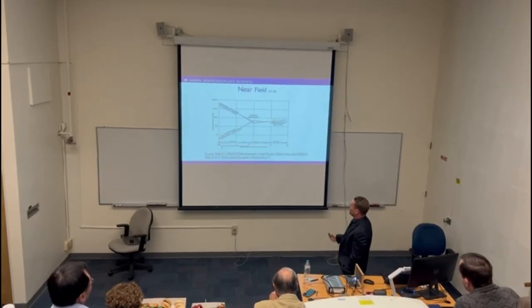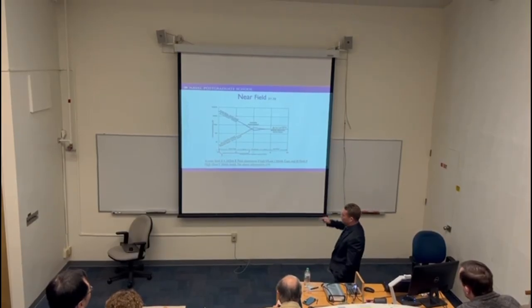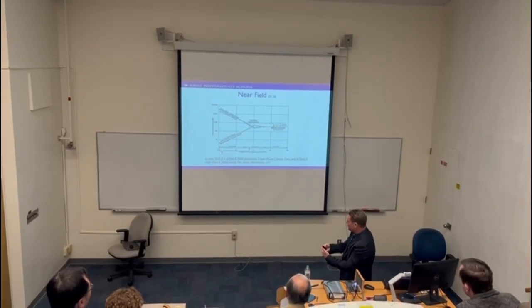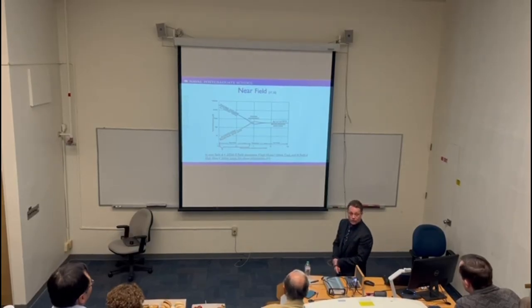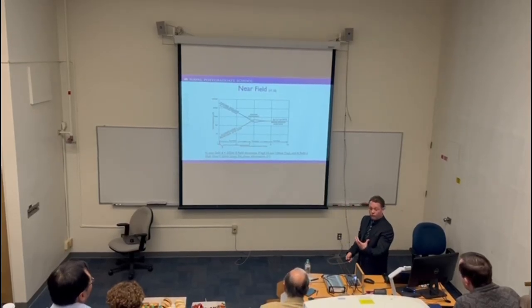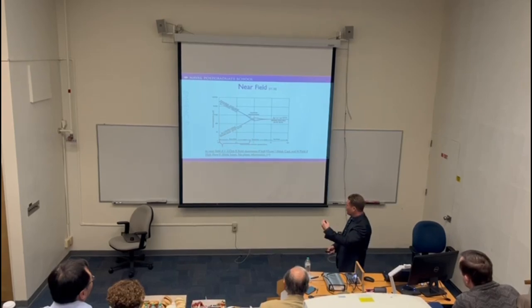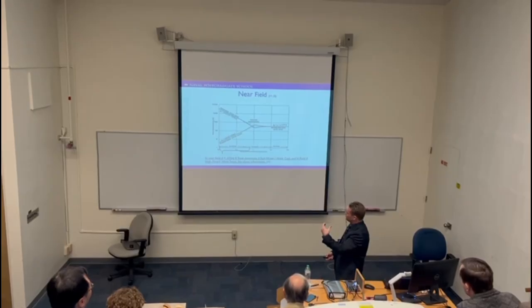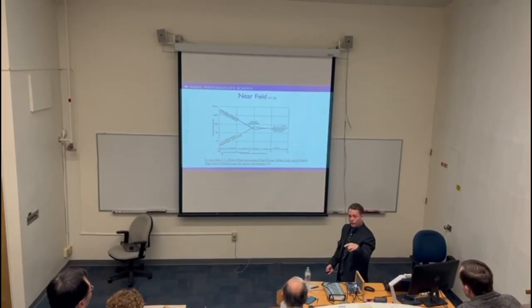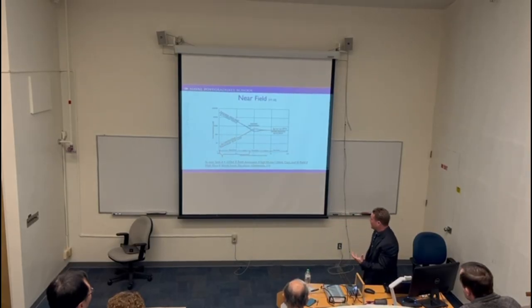Okay, a few little basics. Like I said, I kind of went over this already. In the near field, we're right up on the device. Think of a capacitor: it can have very high voltage, but low current because it's very high impedance. That's going to create a different type of field. The H field you can think of as very high current, low voltage. In my case, I have high current; it's literally a short, the current is flowing through that core, and it's creating an H field.